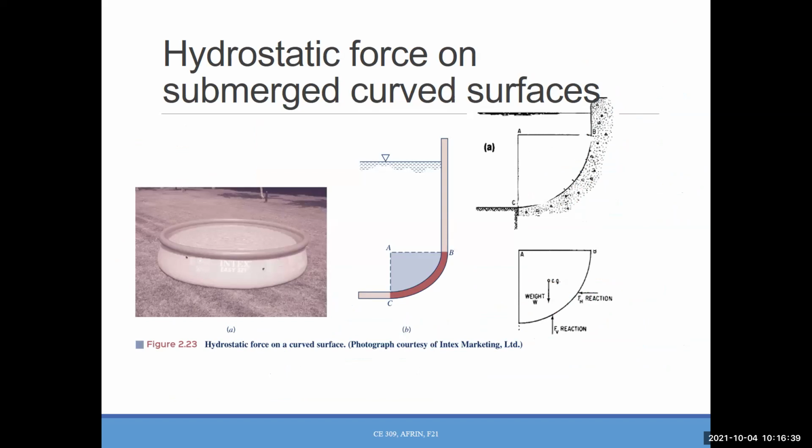You will get the magnitude by P equals gamma h, and you place all the force or pressure perpendicular on the surface. So let's do that. Here, this is a surface which has a circular shape, and here it is 3 feet, and maybe the diameter of this one is 2 feet. I don't know why I'm using 3 feet all the time. It's just an arbitrary number. Okay.